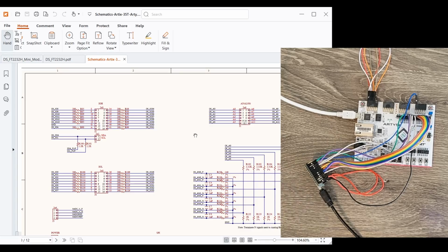And once we have that, we can use the FPGA and create different types of applications, such as software-defined radio, logic analyzer, and oscilloscope, which we are going to do. Actually, in ADALM-Pluto, Zynq FPGAs have been used, which have the USB2 PHY in them.